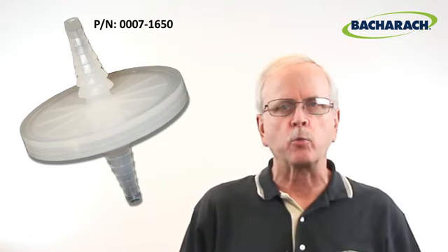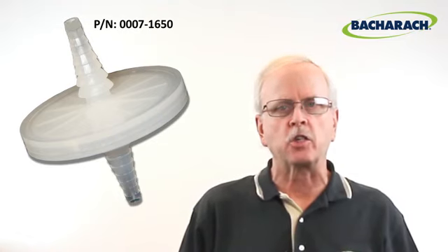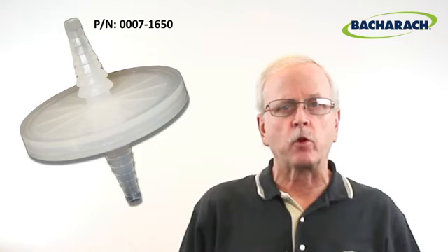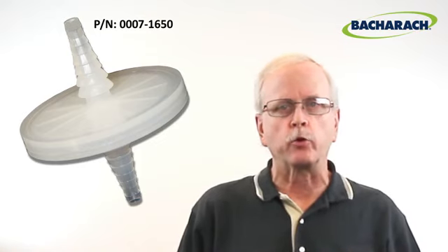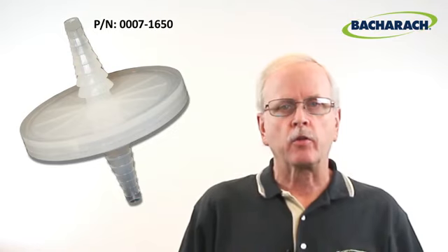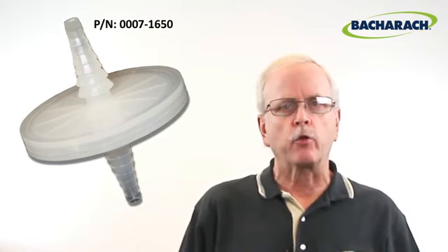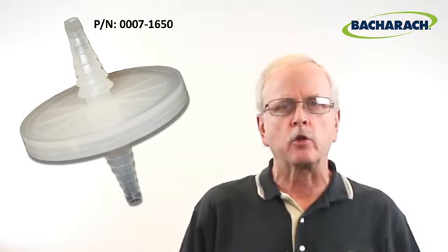The filter prevents moisture from entering the infrared bench assembly. Replacement of a compromised infrared bench is much more expensive than a replacement of a filter. If the filter removal did not clear the no-flow faults, you need to continue your investigation.